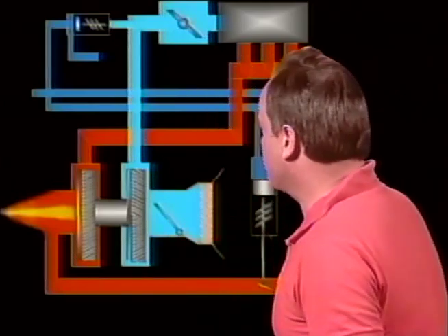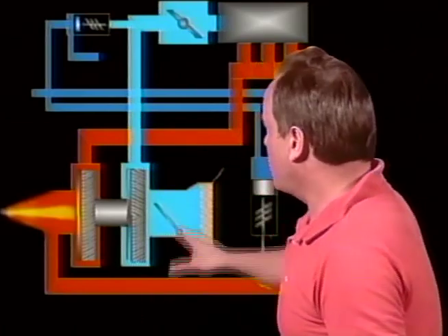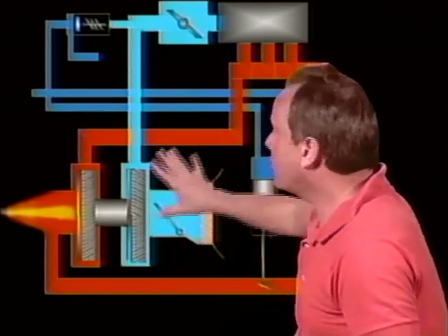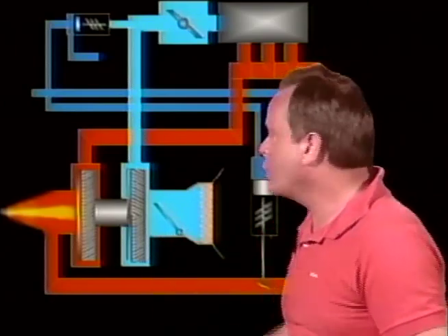So both turbochargers and superchargers, according to the FAA, are superchargers. If it's internally driven, it's what we call a supercharger, and it's driven by the engine itself. If it's externally driven, the FAA calls it a turbo supercharger or an externally driven supercharger, and it's what we call a turbocharger. And what drives an externally driven supercharger? The answer is exhaust gases driving a turbine are used to drive an externally driven supercharger. So on the test, if you see something called an externally driven supercharger, what in the Sam Hill is that? The answer is that's a turbocharger. That's what everybody else besides the FAA calls a turbocharger.